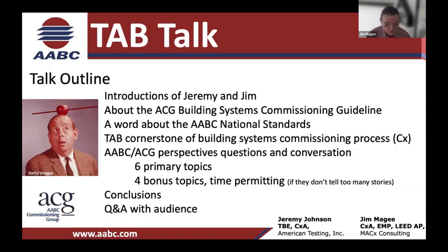Test and balance is one of those cornerstones for the building systems commissioning process, because it ensures that HVAC systems achieve their design intent and that they operate at peak efficiency. And HVAC systems really affect more than just themselves. They affect almost all the other systems in the building. So it's a crucial part of what we do in the commissioning process. For years, AABC has talked about total system balance as an element of HVAC commissioning. I ascribe pretty much to that.